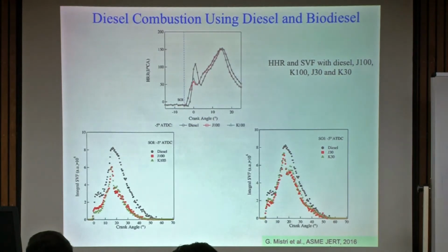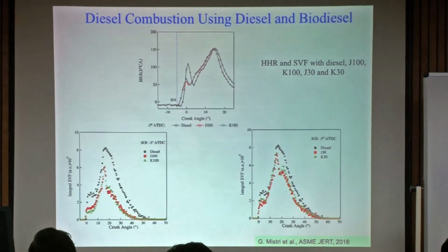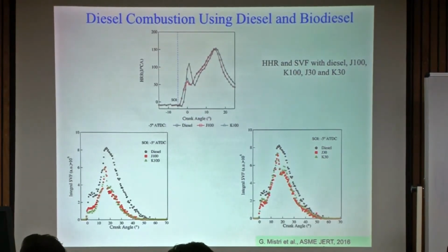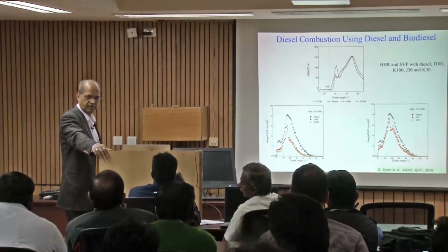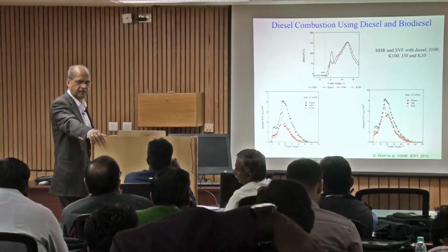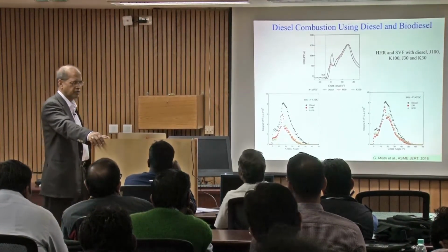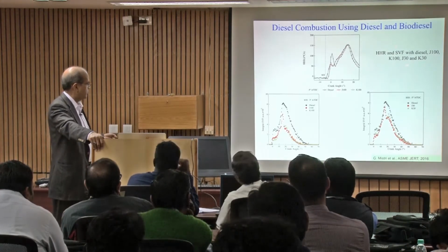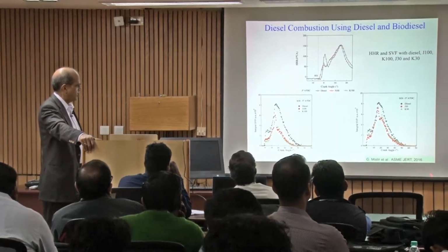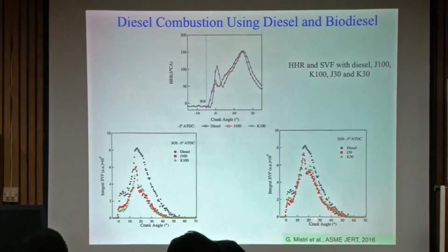It's like a late injection, right? -5 degree. And then you are going up to, the piston has now moved 20 or 30 degree down. It is almost constant volume when the combustion occurs. The changes are only large when the crankshaft goes very far, right? So you can call it approximately constant volume. Pressure increases a lot. In the paper they have the pressure plots also, so you can look at that.